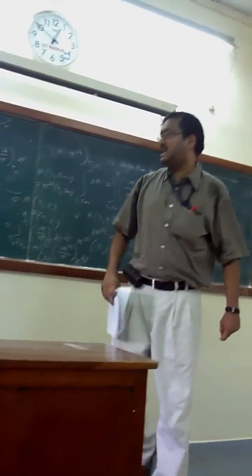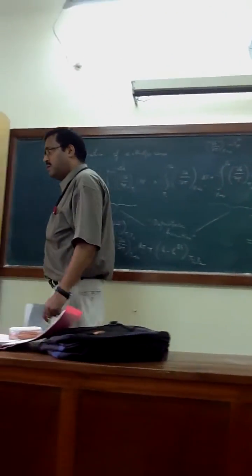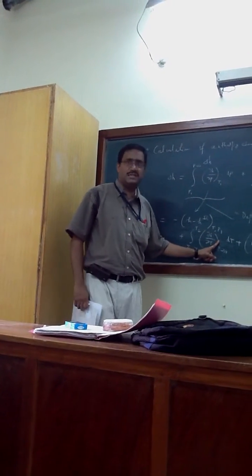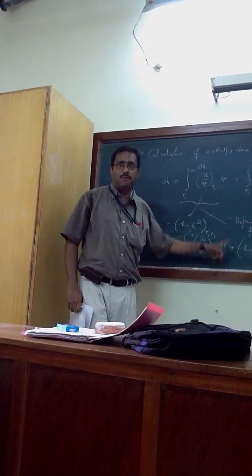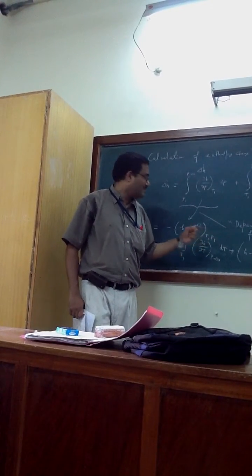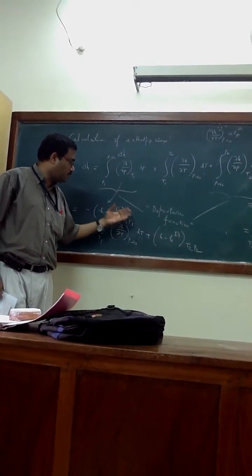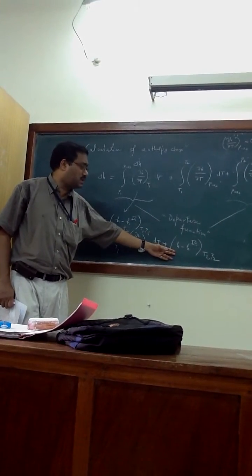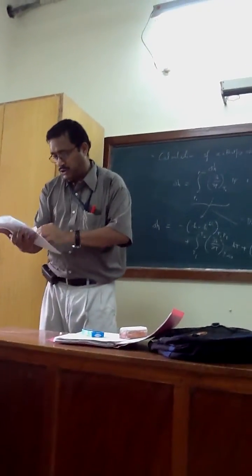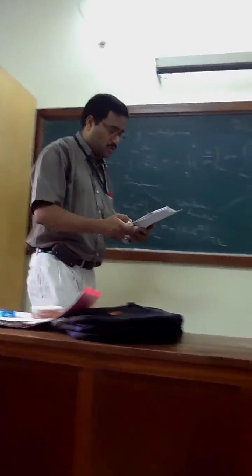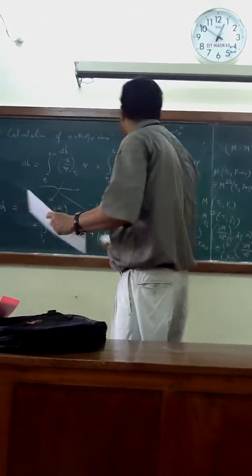So enthalpy change is nothing but negative departure function at temperature T1, P1, plus this integral, which is Cpig dT, plus departure function at T2, P2. If you have a generalized departure function, you can actually evaluate the departure function in a computer program and just substitute T1, P1, and you will get this expression. You already have this and you can calculate delta H. So I will proceed next to calculate. So what we have learned, H minus Hig.